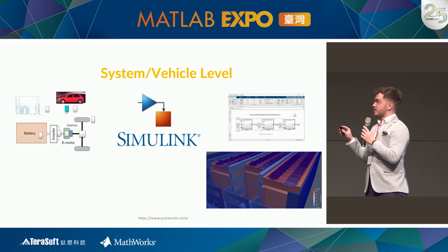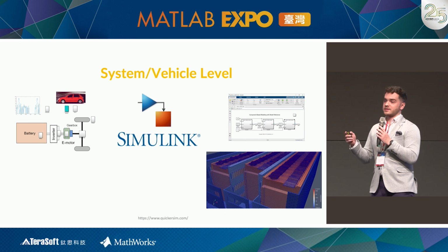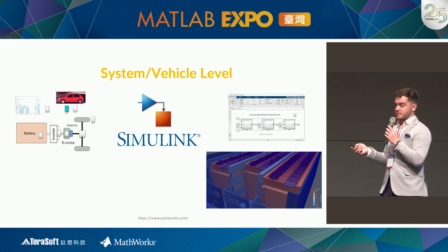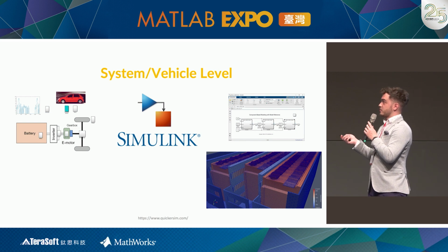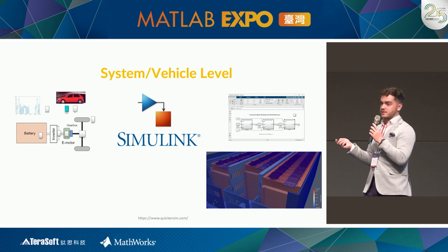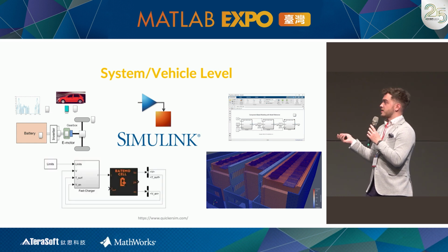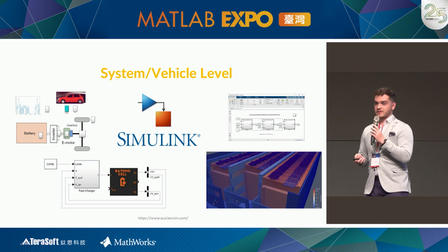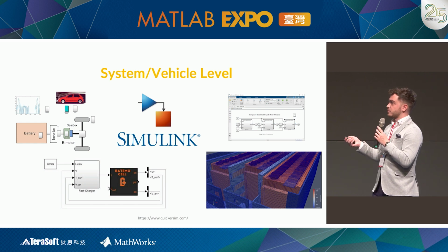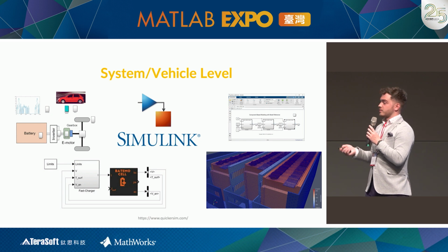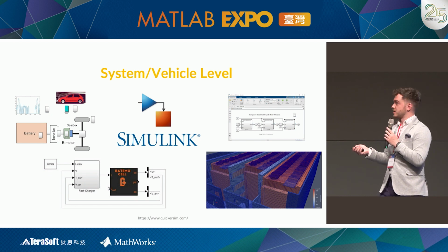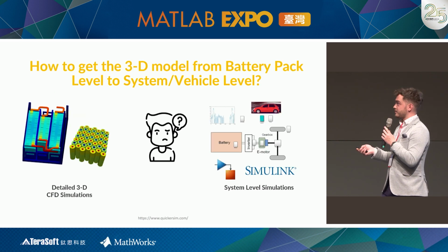You can get the exact temperature at the point where you would normally have your temperature sensors, for example. And if you want a more accurate electrical model, you can use external battery electrical models. For example, you can either build your own model using Simulink blocks or Simscape blocks, or you can use external companies' models, for example, like Batimo.